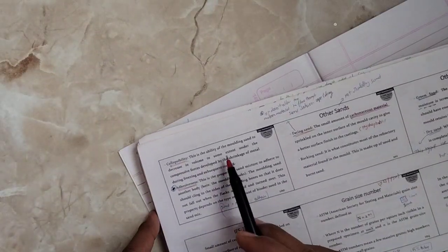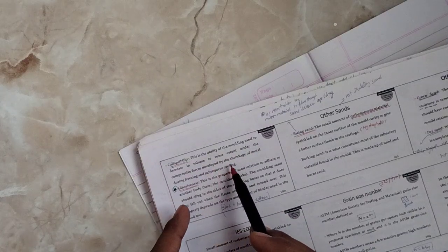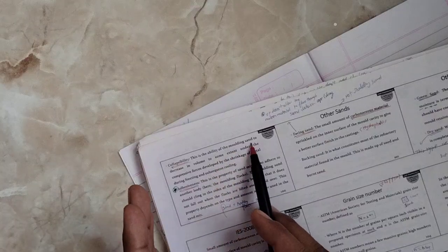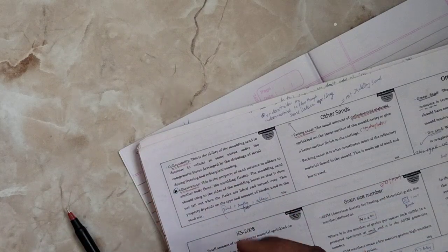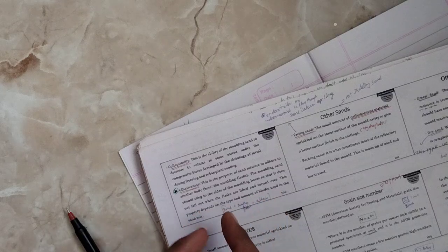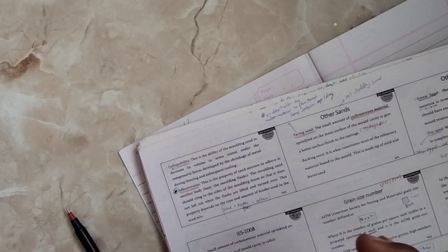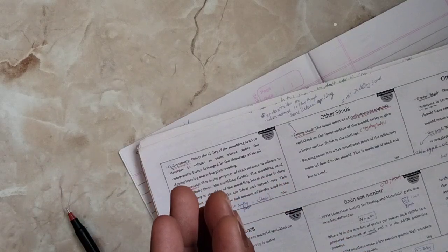So next one is collapsibility. Collapsibility is the ability of molding sand to decrease in volume to some extent under the compressive force developed by the shrinkage of metal during freezing as well as the subsequent cooling. Because you can see, guys,